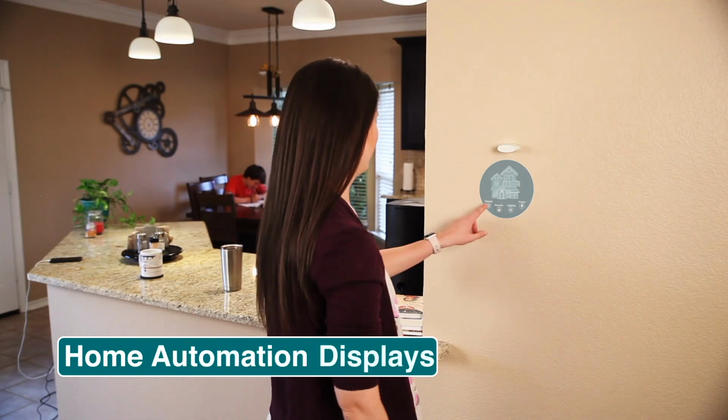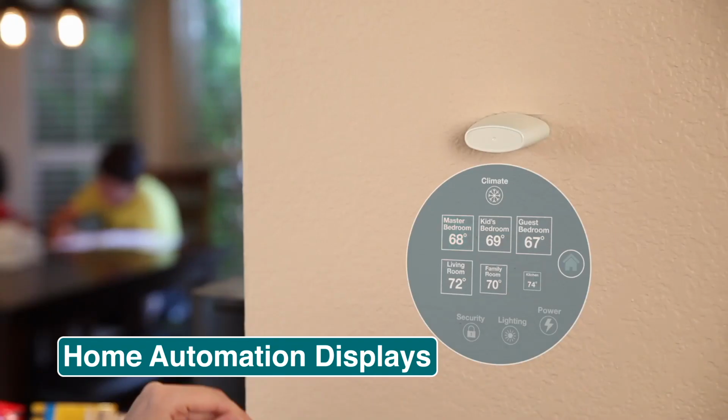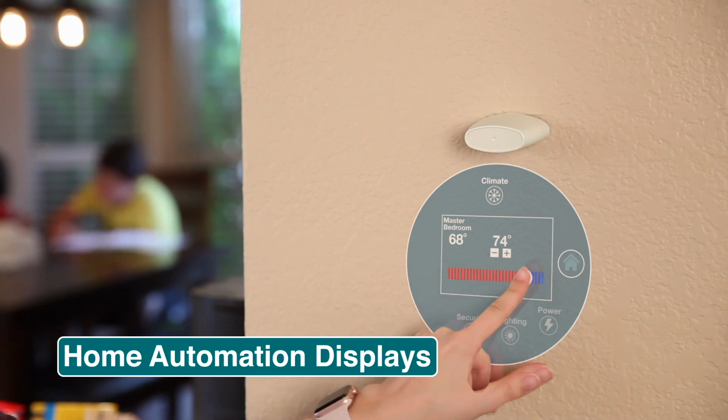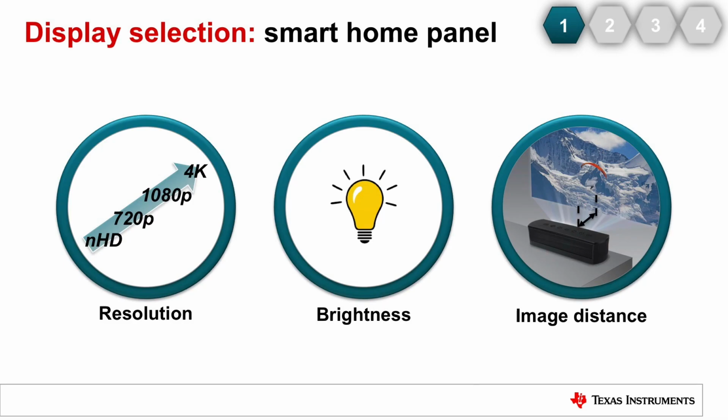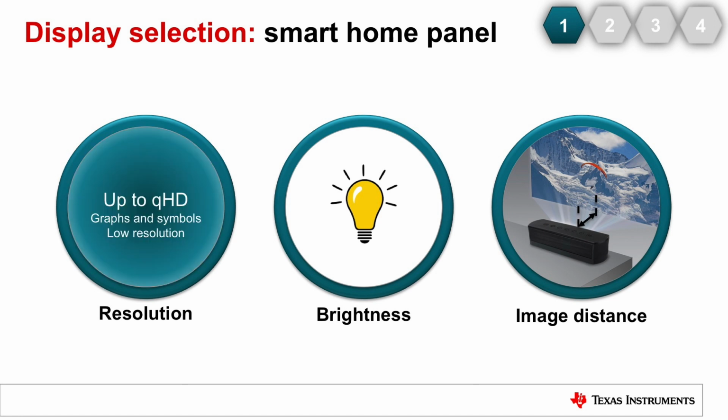In this video, we're showing an application for a smart home display. Now what we're gonna do is look at each variable and determine what are the best options. To look at our variables for this display, let's start with resolution. Obviously the display size for this is probably less than 10 inches, and so a resolution of QHD, wide VGA, even NHD may be adequate, given that we're only using graphs and symbols. So in general, a low resolution is probably required for this display.